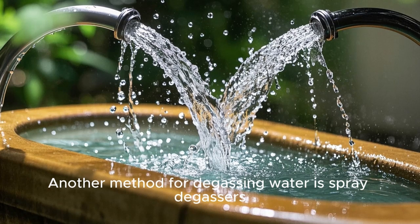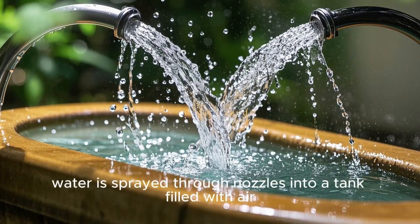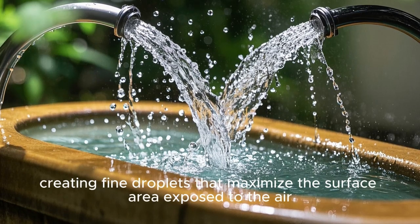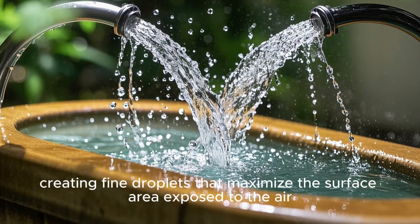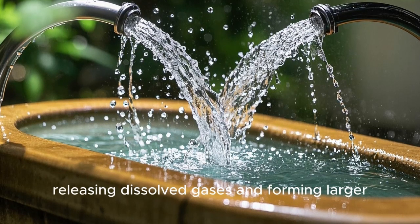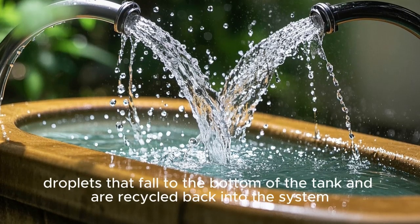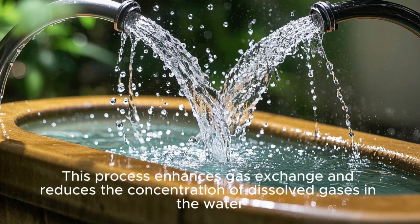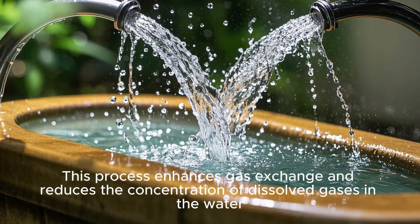Another method for degassing water is spray degassers. In this method, water is sprayed through nozzles into a tank filled with air, creating fine droplets that maximize the surface area exposed to the air. The water droplets quickly coalesce, releasing dissolved gases and forming larger droplets that fall to the bottom of the tank and are recycled back into the system. This process enhances gas exchange and reduces the concentration of dissolved gases in the water.